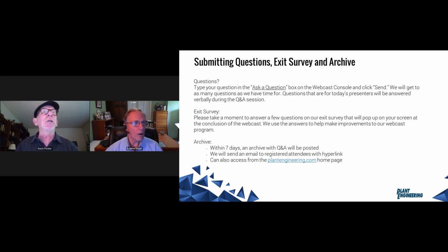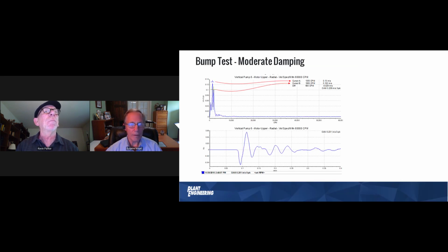Could we go back? Not at all. Let me go back to slide 17. There we go. Okay. A bump test. We had a machine. We said, it's got high vibration. I just wonder if there's a natural frequency close to the rotating speed. So we shut the machine down.